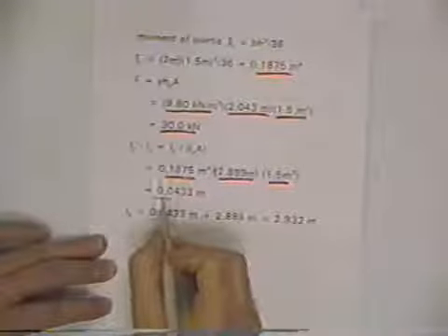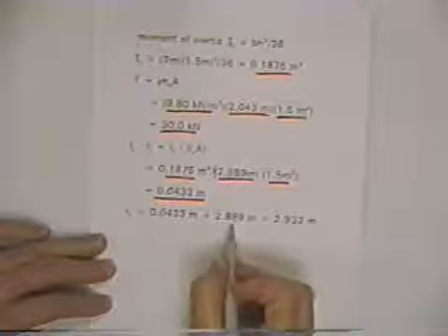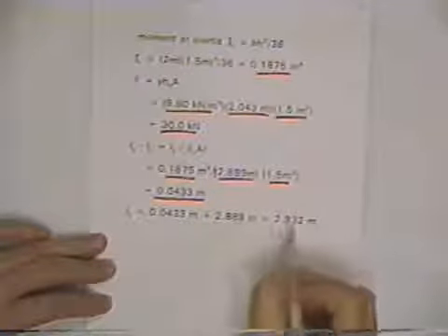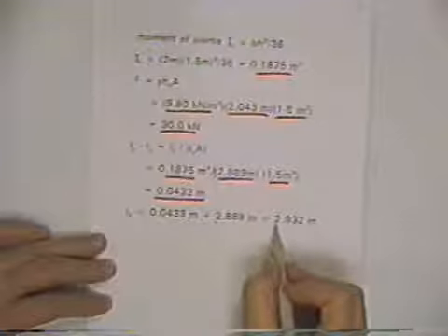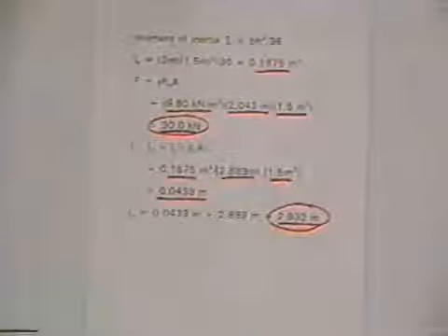And we've got the moment of inertia, which we've computed here, which we can plug in. So we've got all the numbers to get that little incremental distance along the incline from the center of pressure to the center of gravity. And we can add that to the distance that we've already computed to the center of gravity to get the length from the water surface along the incline to the center of pressure. Okay, and so that gives us the force and the location of the force using the first set of formulas.